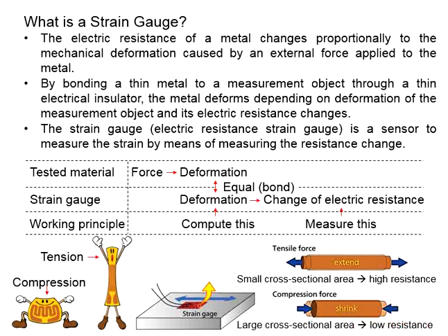Now the concept is this. Under normal conditions, the strain gauge itself has an existing electric resistance. Now when the strain gauge is subjected to tension, the cross-sectional area reduces and the resistance increases. If you are able to quantify the electric resistance, since the relationship is proportional to the deformation, you are able to quantify the strain.